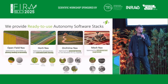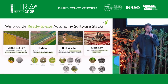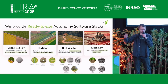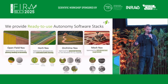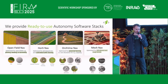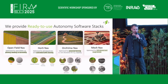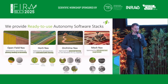So in different fields we see, for example, in open fields we can draw polygons, and then the route is computed autonomously, and the robot can drive it also with different sizes of the headland. In horticulture we always have these beds, so row following on beds, and in orchards and vineyards, we have these perennial structures like trees, bushes, also hops, and so on. And then when it comes to mesh navigation, so like navigating in really uneven forests or hilly vineyards, but also Moon and Mars or so, then we have something which I want to present a bit more in depth today.